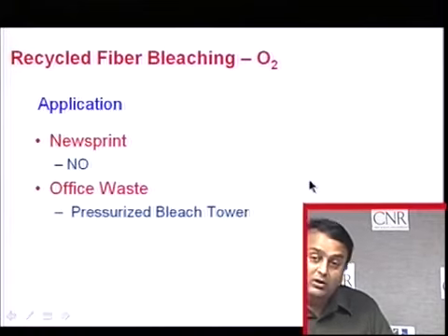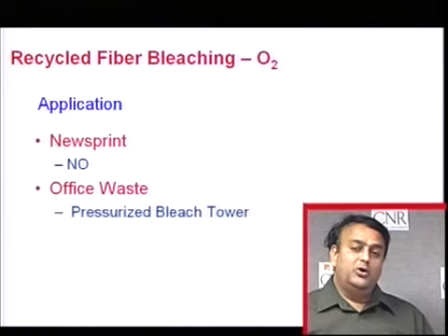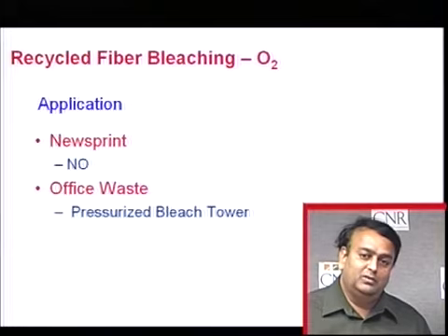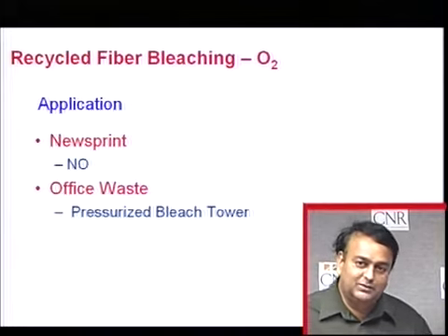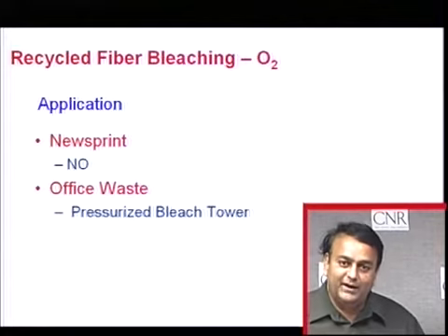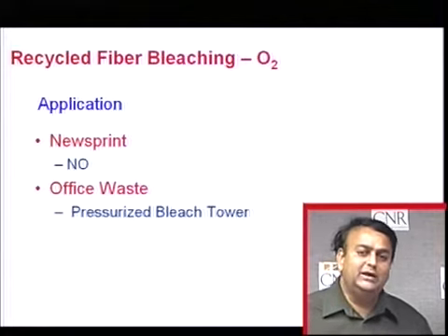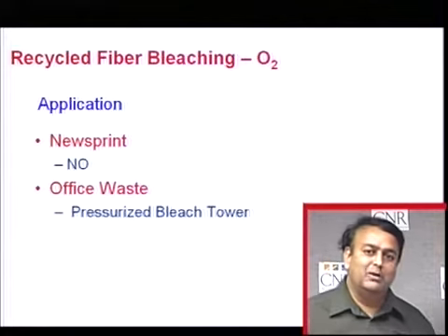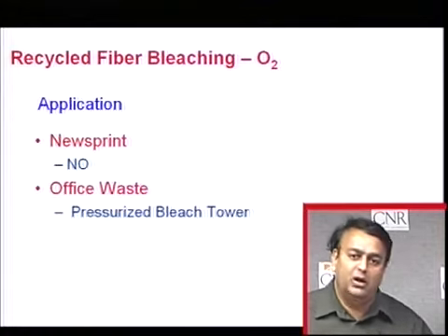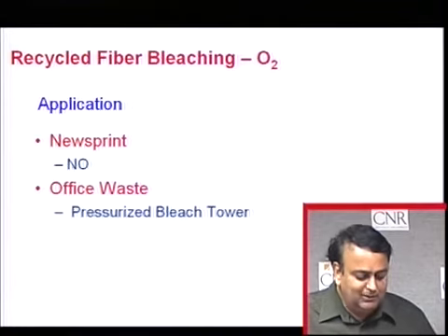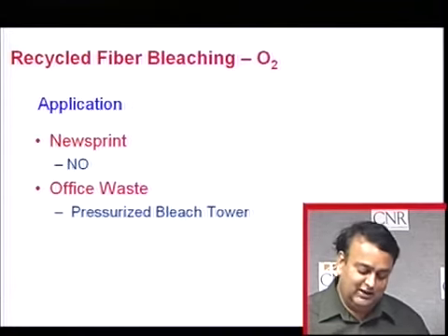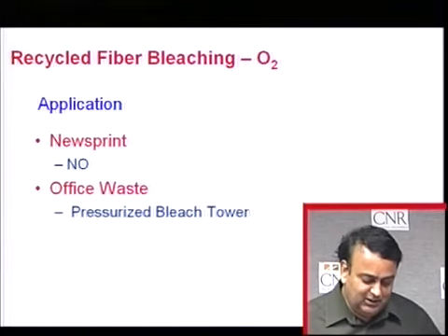Where do you apply oxygen? You don't put oxygen on newsprint recycling because it's going to yellow the fiber. There is a high amount of lignin present. Oxygen is a good delignification chemical, but because of the such a high kappa number on the newsprint, you may bleed the lignin, you may make the fiber yellow. So what you need is a pressurized bleach tower for office waste. That's where oxygen is going, like shown in the previous diagram.